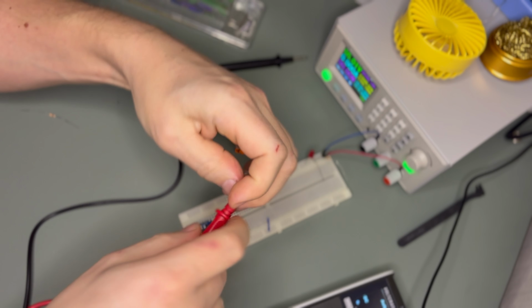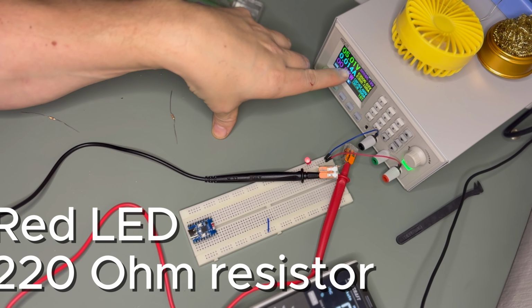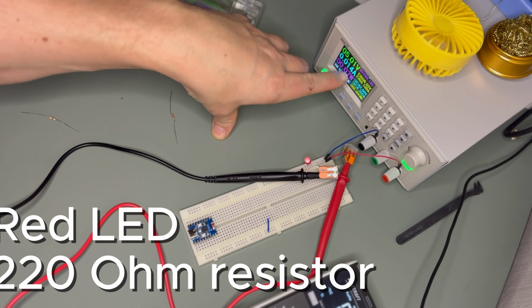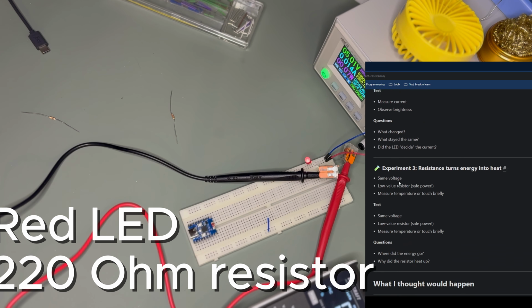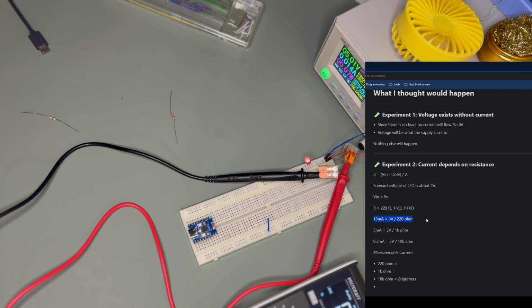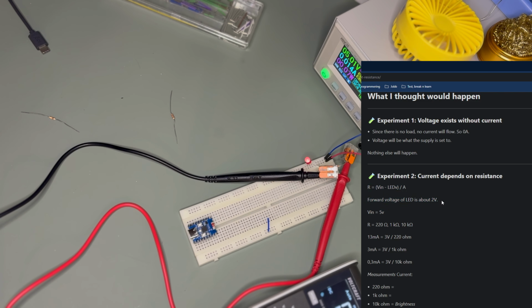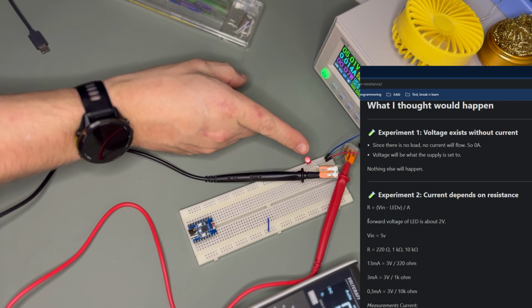Okay, so now we have 10 milliamps. My power supply says 14 milliamps. I wrote down some numbers here. With 220, I was guessing 13 milliamps with this calculation. I used 2 volts as a forward voltage over the LED.